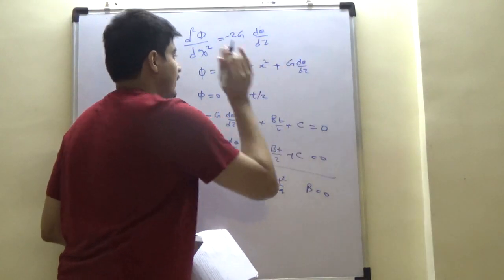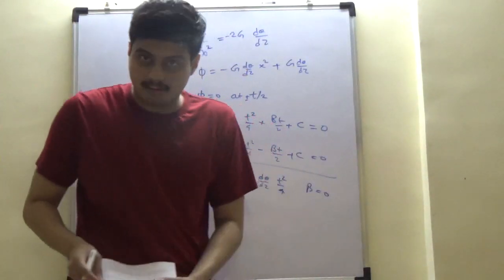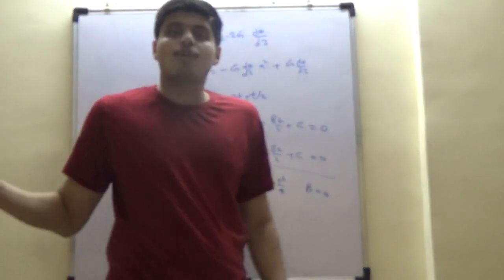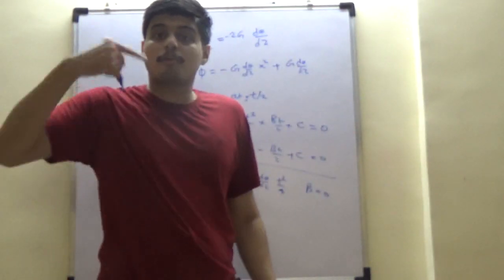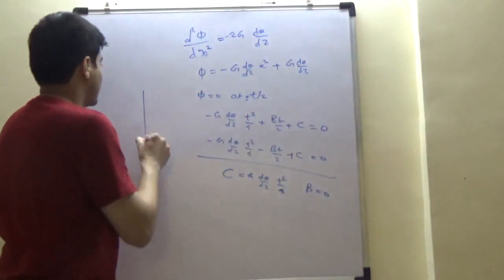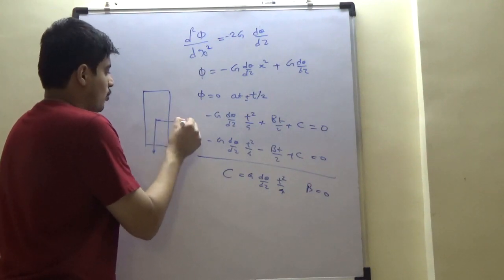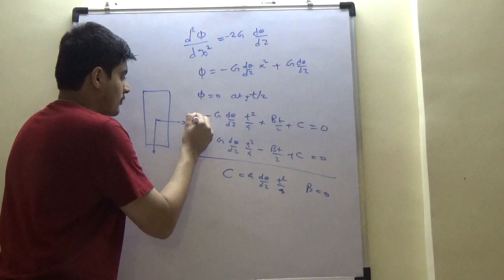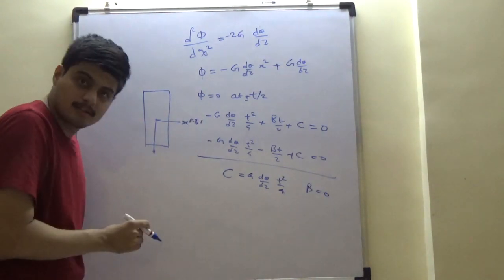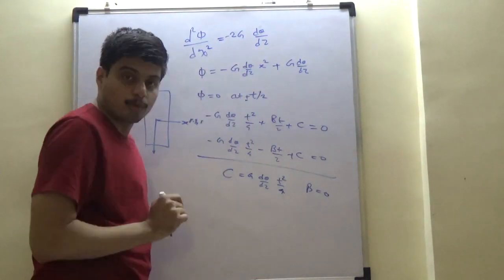And we expected this, right? Any linear variation with x, by simply changing the frame of coordinates, you will have a problem because it will have x minus L, a constant error building. So even from mathematical induction, see how I am reasoning this. Any x variation which is an odd polynomial, 1, 3, 5, cubic splines, cannot be tolerated because they can never be harmonic.